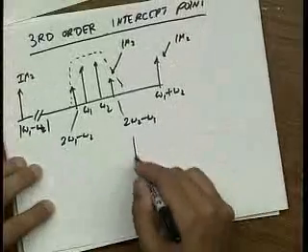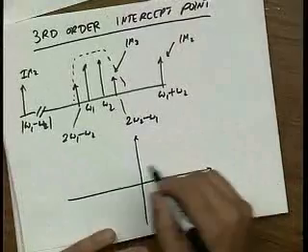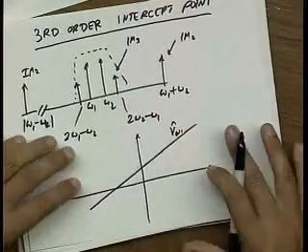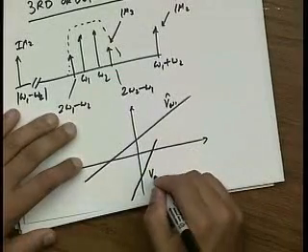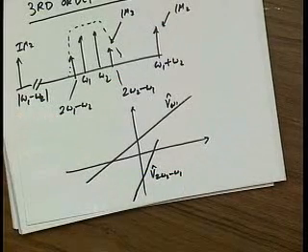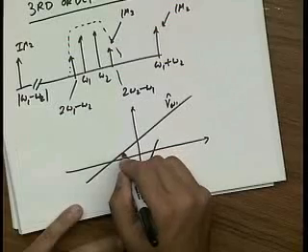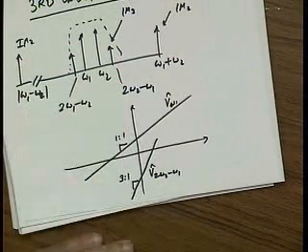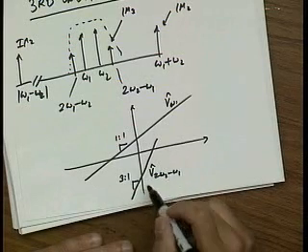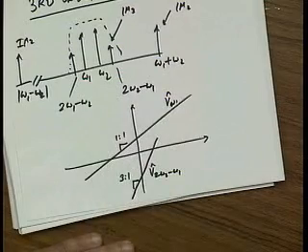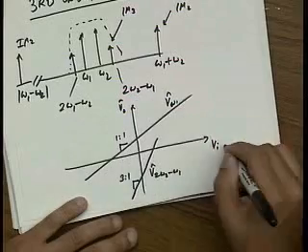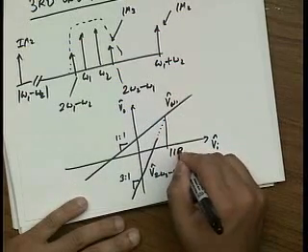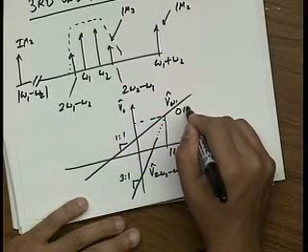Now if I do the same thing that I did graphically, I can again make a plot of my fundamental output. This is V_O omega 1. And then I can make a plot of, let's say, V at 2 omega 2 minus omega 1. This is the amplitude of the third order. And now you'll notice that if the slope here is 1 to 1, the slope here is going to be 3 to 1. That's because we know intermodulation goes like the cube of the signal. So this IM tone catches up very quickly because it's moving 3 times as fast on a log scale. And again, I can define the intercept point. I call this my input IP3 point, and this point my output IP3 point.